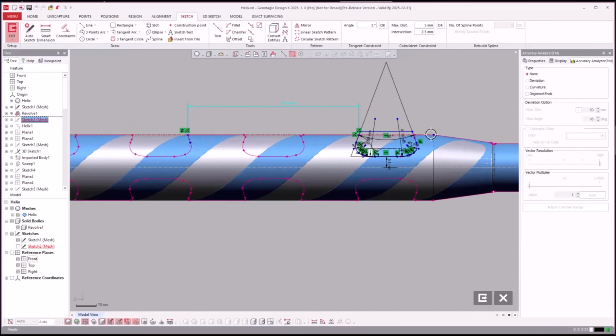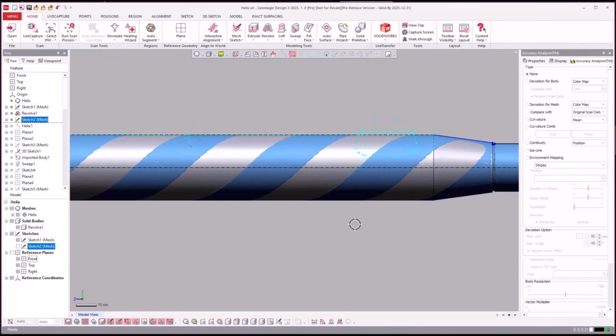We also need to know the diameter of the shaft, and then how many revolutions we're going to go down the thing, down the surface. But this is why we're creating this measurement here, is to understand mainly this piece of information and the diameter. And you can also create this reference geometry to reference in the Helix sketch later, which you'll see here in a second. So we'll go ahead and exit out of here and keep on moving to the next feature in the tree.